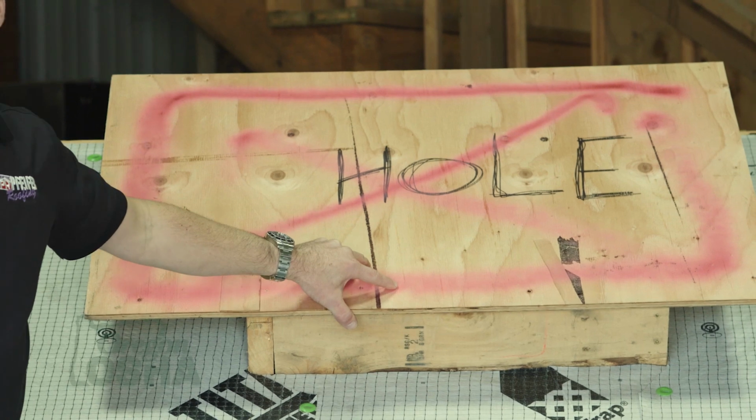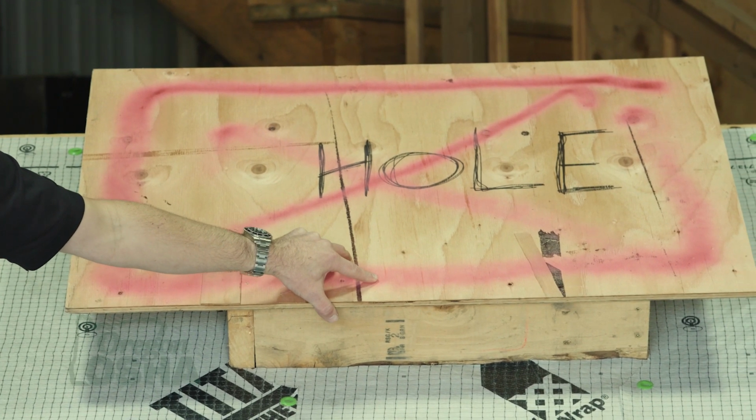What we do is build or take a sheet of plywood and cover those skylight areas, so that we can eliminate the risk of falling through the opening, or tripping and then falling through the skylight itself. Taking plywood and covering those holes or skylights is critical, and it happens at the very beginning of a job. When the foreman gets to the job, they look at their material list and the job sheet, see there's a skylight, and know they need to address it right away. So when they go up and get their fall protection installed, they will take care of that skylight as well.